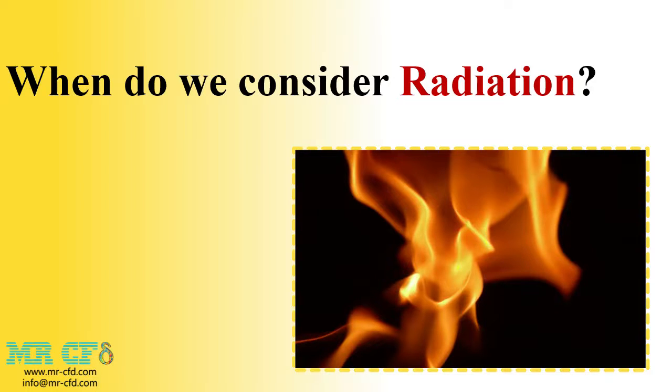The main cause of this heat transfer method is the vibrational and rotational movements of molecules, atoms, and electrons. Therefore, these vibrational and rotational movements are equivalent to the temperature value. An increase in temperature leads to an increase in the rate of radiant heat transfer. In fact, radiation depends on temperature according to the Stefan-Boltzmann equation, which I will explain in a few moments, so that the temperature has the fourth degree or power.